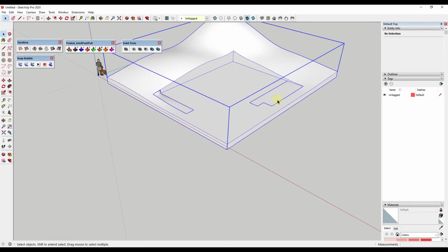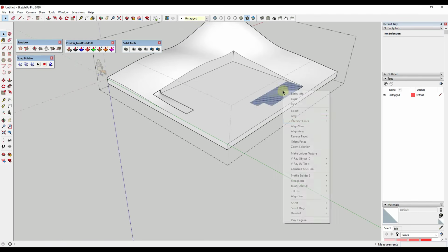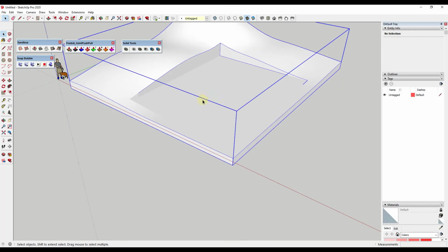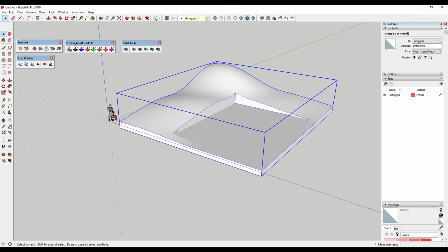And if you still have these perimeters in here, you could double click, then come in with the eraser tool and hold the shift key in order to hide the edges around the perimeter. We can make everything look a lot smoother by doing that. So you can use this in order to create this very smooth looking flat site inside of a 3D shape.